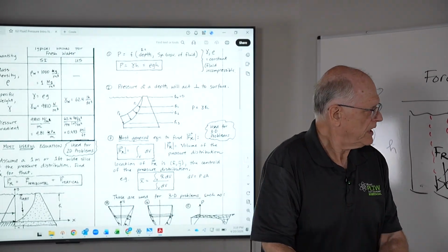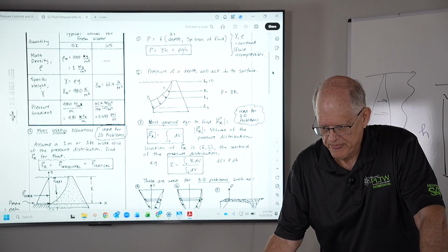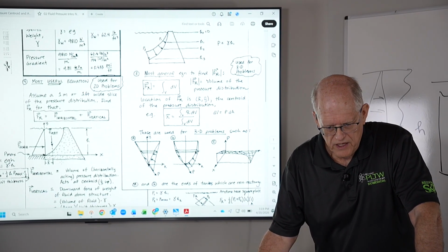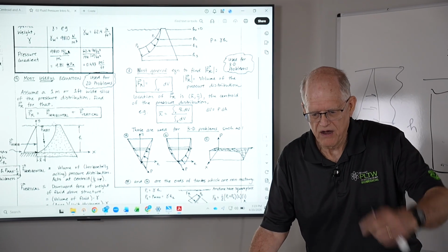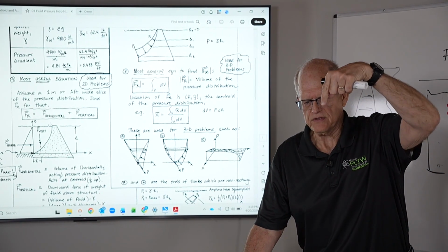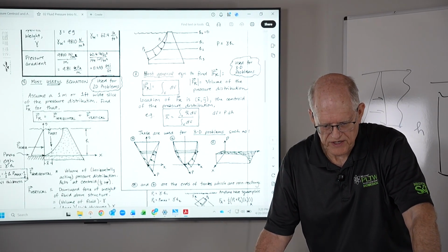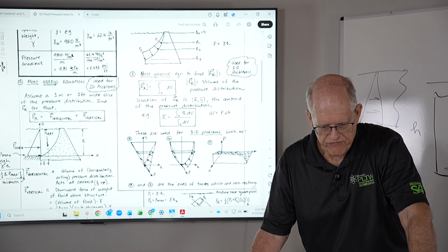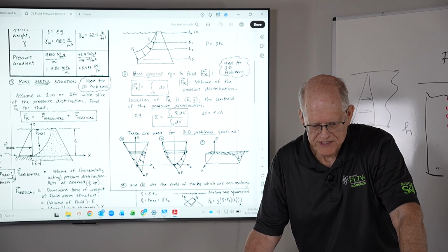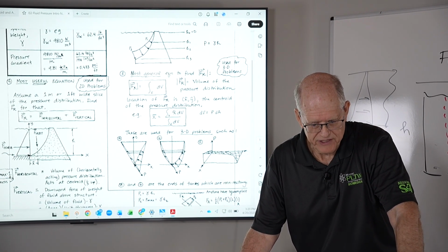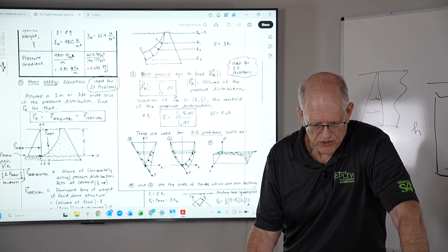And so in general, if you have a curved surface, the weight of the fluid above the curved surface is the vertical force. And it acts at the centroid of this area. And the horizontal force is basically the same horizontal force that would act on the cross-section of this dam, which basically in general is like a triangle if the dam comes up to a free surface.